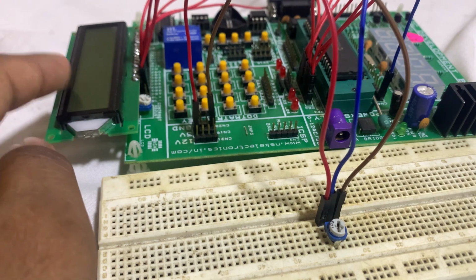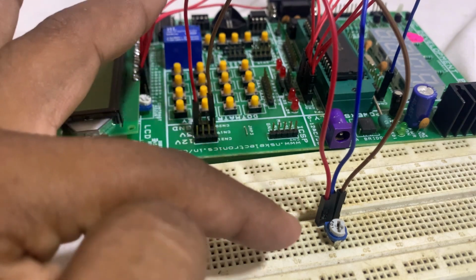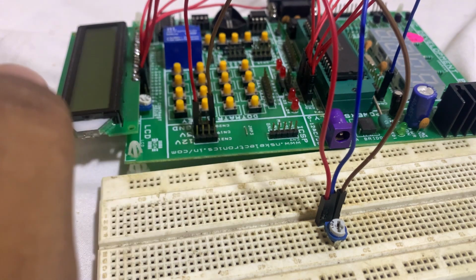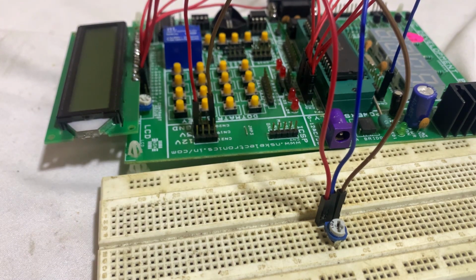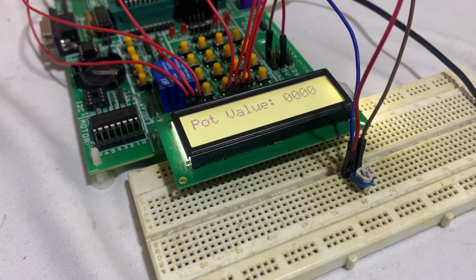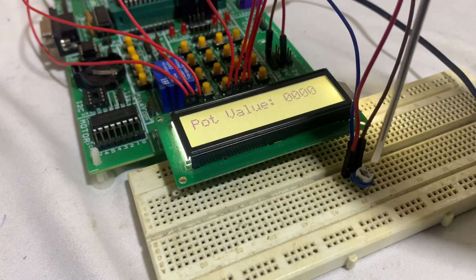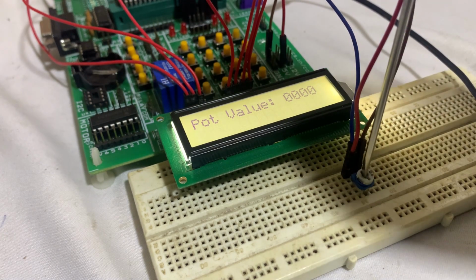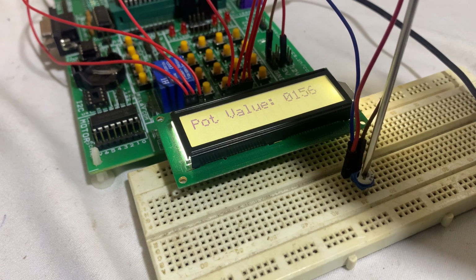We have successfully connected an LCD in 4-bit format, and we have connected a variable resistor to the RA0 of the PIC16F877A. And let's see the output in the hardware. Now you can see I am having the port value to be 0 because the knob of the potentiometer is placed in the extreme ground end. And when I rotate the knob of the potentiometer towards the other extreme end, you can see the port value increases based on the knob rotation of the potentiometer.